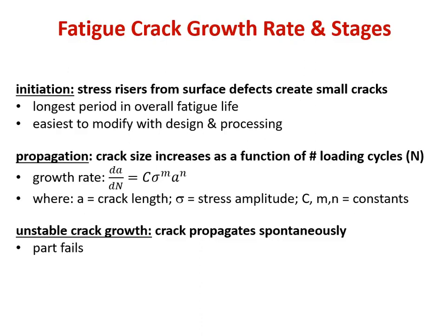So initiation for a fatigue crack is when stress risers, usually from surface defects, will actually create small cracks. Again, this is the longest period in the overall fatigue life, and almost always results from surface defects. If you want to stop fatigue cracks, you stop it in the initiation stage.